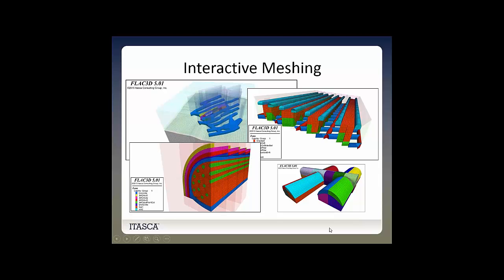block of mesh. Therefore, grid generation interactively is a rather tedious operation, but which has, as a reward, the possibility of controlling the grid distribution, the local density, the orientation, and the sizing of the elements. That's very important, especially for civil engineering applications. As you will see in automatic meshing, that capability is somehow lost.